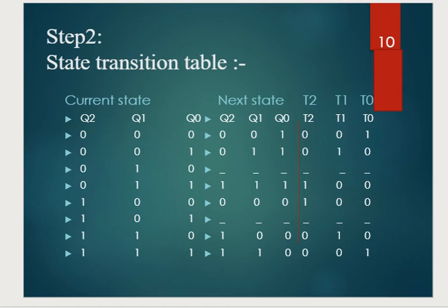And we're going to use a 3-bit counter, because the number of flip-flops is going to be 3, since we're going to use 3 bits, and that depends on 2 raised to power n, where n is 3. You can see 2 raised to power 3 is 8, so we got 8 combinations here. On the basis of these, like I told you, we can derive this table from the excitation table.